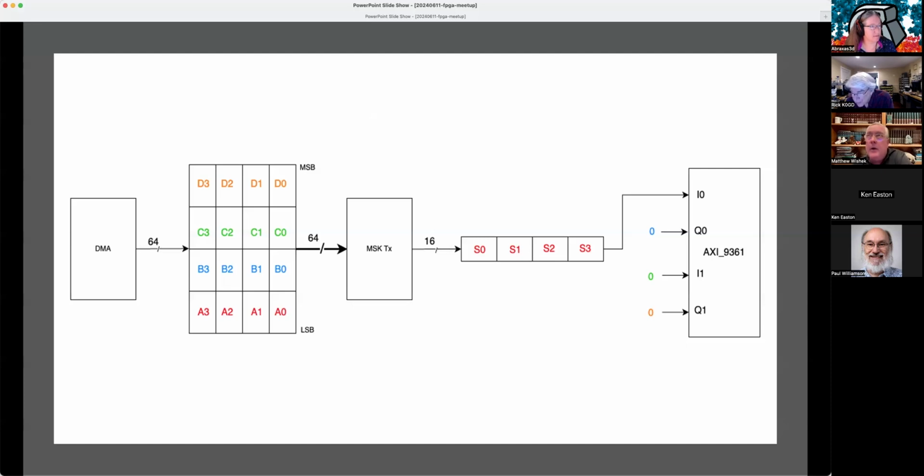In my simulation right now, the data rate is 15.4 kilobits, and I have an IF. The IF has to be a multiple of 1/4 the data rate, so that the zero crossing of the IF matches the zero crossing of the symbols. And then I'm running it with the sample rate.